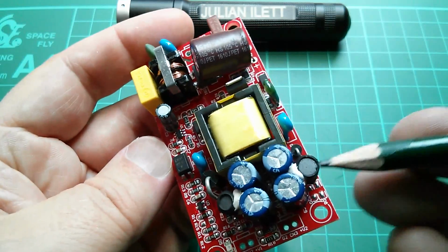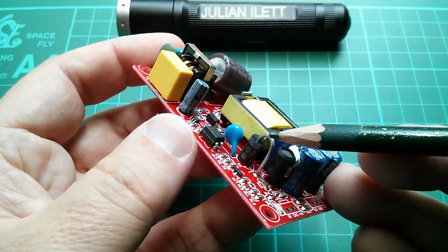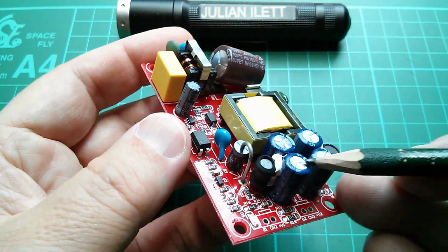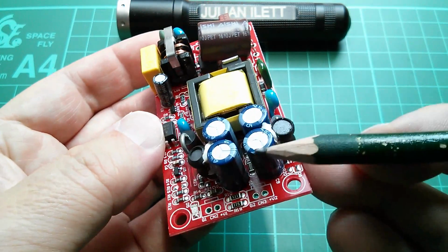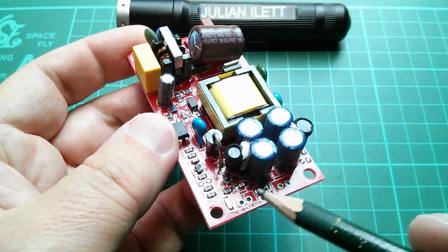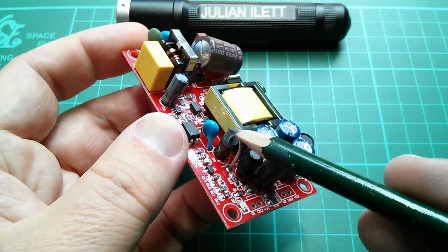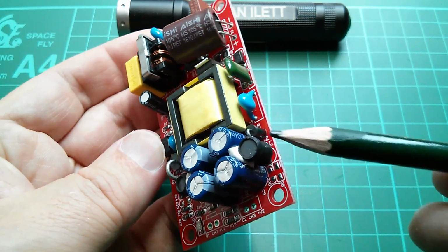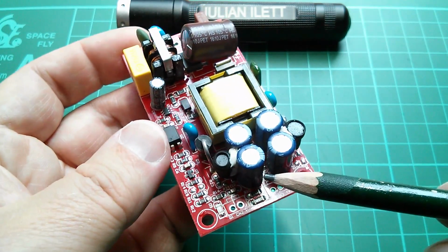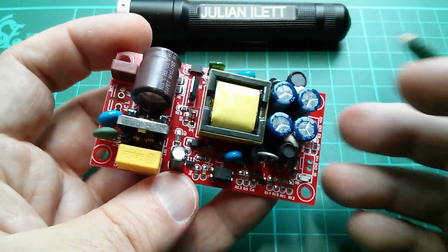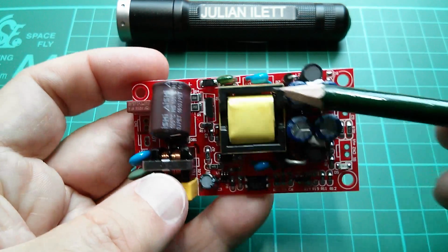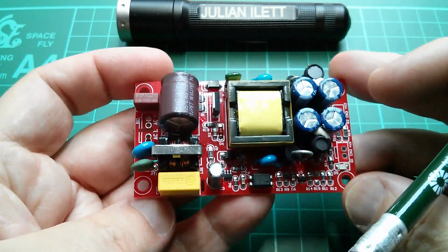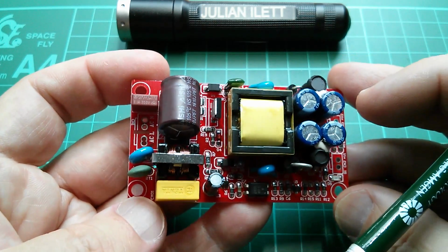And then we can see the two outputs. Now there's a big diode there with an inductor and a couple of capacitors. And on this side a smaller diode with an inductor and a couple of capacitors. So I'm just wondering whether this is the 5 volt end with the bigger diode for more current. And this is the 12 volt end, but I guess we'll find out in due course. So yeah, some more capacitors over here and here. So lots of really interesting stuff on here.